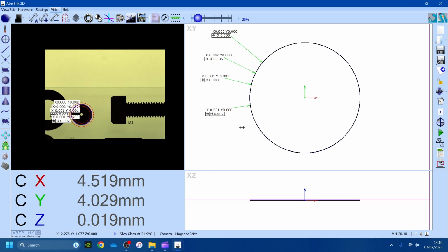Now finally, as a final note, it's worth noting that if you don't mechanically adjust the camera, you can now switch between the probe and the camera, and you don't need to run these calibration checks every single time. So once it's done once, it should be good for a long time to come. But there's no harm in running these calibration verification programs on your Graticule just for peace of mind should you have any issues.